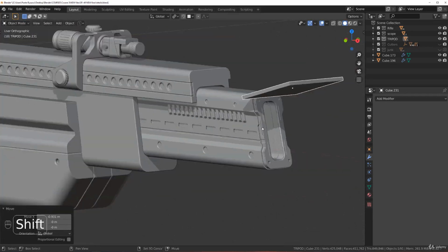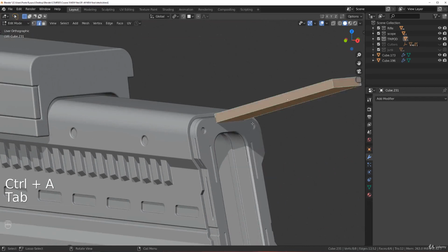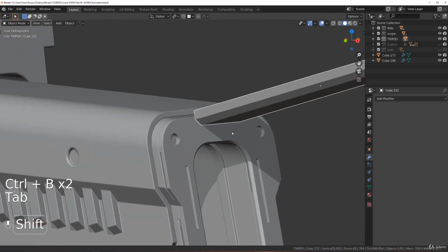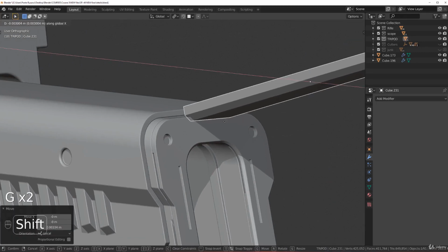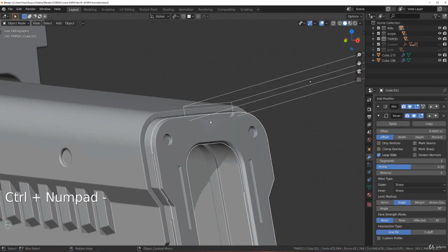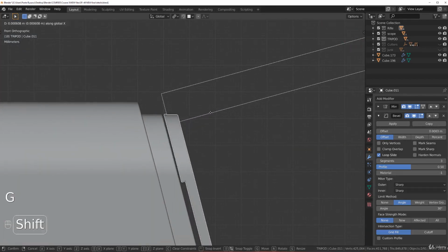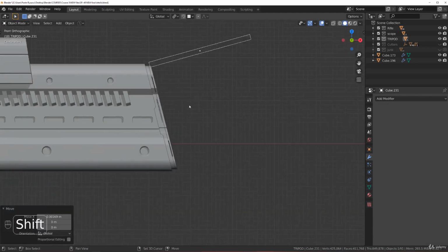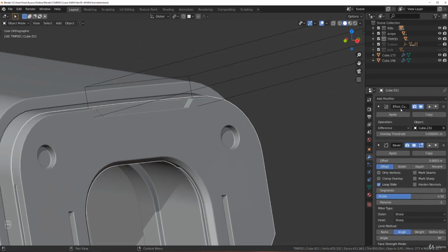Now let's see, SY, scale it, then apply scale and select these 2, chamfer them. What the? Chamfer them, yes, and then move it higher, ZZ and move it higher, and GX, move it in and simply slash it. And I don't want to slash it through, I want to slash it a little bit, whoops, like almost through. Okay, and then we're going to, let's apply Boolean here to the top.